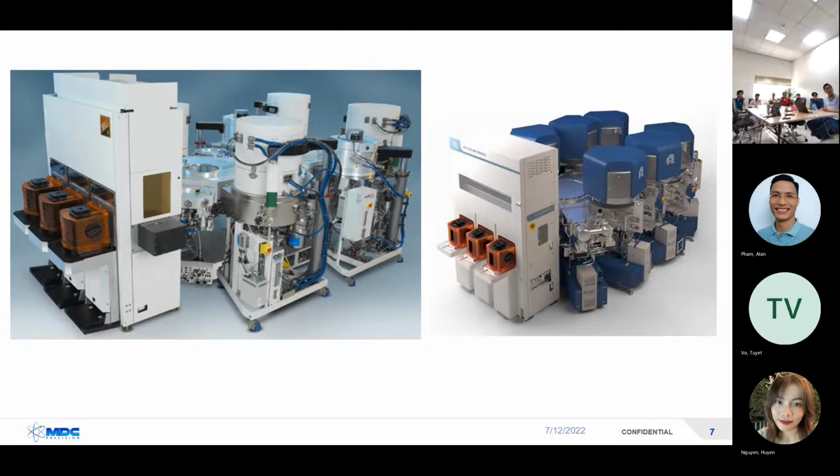Okay, so those wafers are sitting in here. Okay? This is basically out like in here, in atmosphere. We can't process at that very fine level in atmosphere. There's nitrogen and other gases and particles out here. So remember, if I have a very pure silicon dioxide film, and I want only fluorine and carbon to help me etch it, if I have air involved or I have nitrogen, the nitrogen is going to chemically react and I'll wind up with nitrogen in my transistor and it won't work. Okay, so that's why we have to do semiconductor processing in a very deep vacuum.